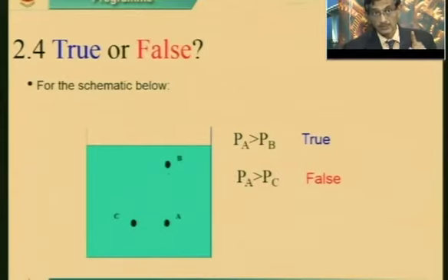Now, at the point A for the same liquid, say mercury, the point C is also at the same depth in the tank. The statement says the intensity of pressure Pa is more than Pc. You may dispute this now because the liquid is the same. So, P is equal to gamma L, same, into H, and Ha and Hc are both at the same position, say 10 centimeter and 10 centimeter. Definitely, I have mentioned here Pa more than Pc, which is not correct. It is a false statement.